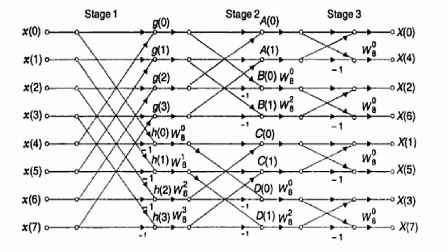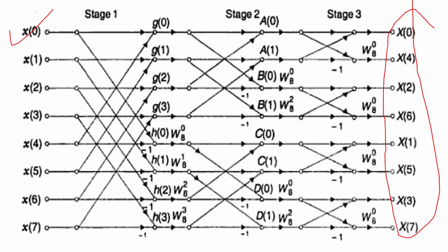So here now if you see, the difference is that in the DIT we are solving, we are keeping first the 1 cross 1 butterfly, then 2 cross 2, then 4 cross 4. Just make it reverse here, 4 cross 4, then 2 cross 2, and then 1 cross 1, right? So again the same process we are going to take, just a bit reversal will be at the output. Here in the DIT we have bit reversal at the input. Here inputs you can give as usual, like 1 2 3 4 5 6 7, and the output will be in the bit reversal, right?